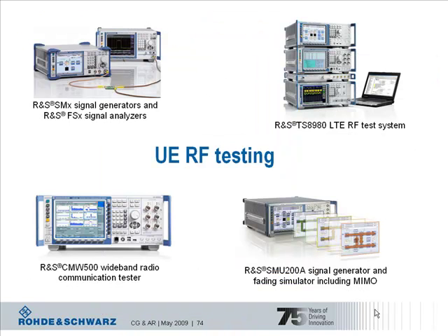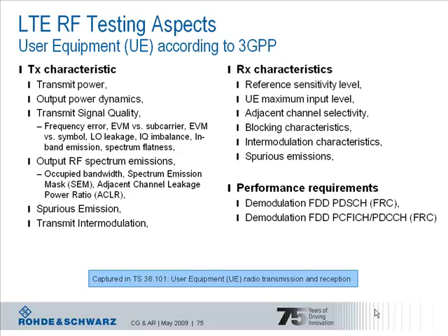With this we stop the short and high-level excursus on eNode B testing. Let's focus now on the terminal side. As for the base station, RF and performance requirements are covered in technical specifications from 3GPP. This is 36.521 Part 1, which relies on 36.101 UE radio transmission and reception. TX and RX measurements as well as performance requirements are specified here.